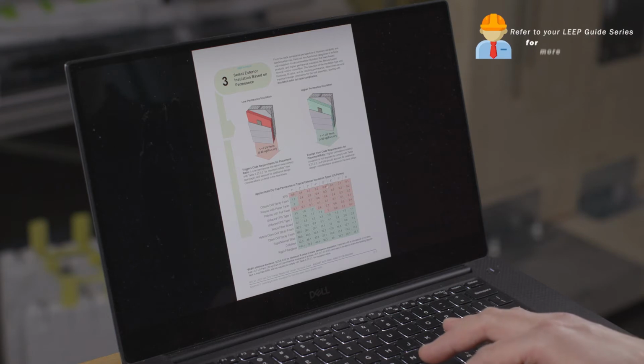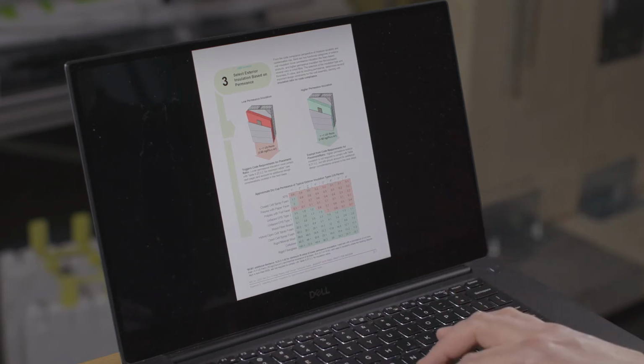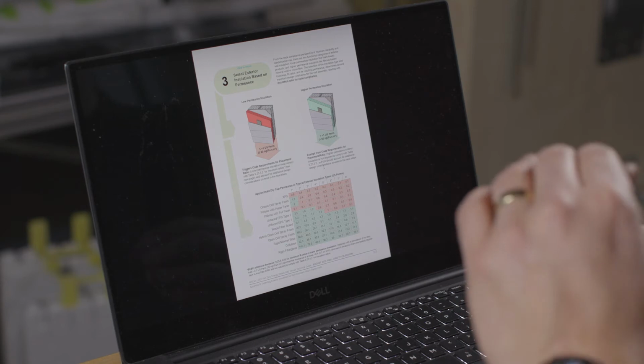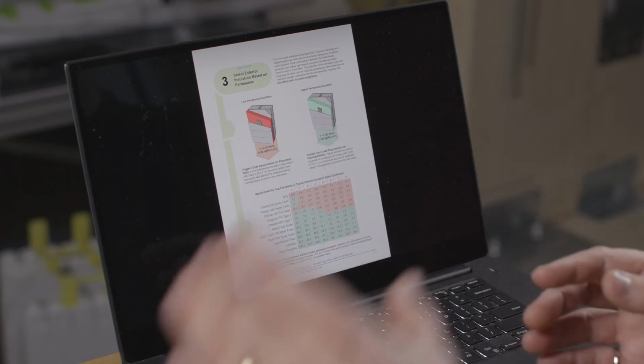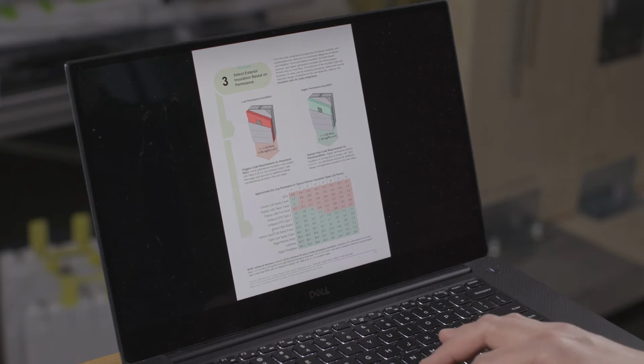The thicknesses we're usually talking about for net zero levels, in that R35 to 40 range on a 2x6 wall, are generally impermeable. So, simplistically, foam plastic insulation can be looked at as low permeance, and things like fibrous insulation, like mineral wool, wood fiber board, cellulose, rigid fiberglass, those tend to be vapor permeable.